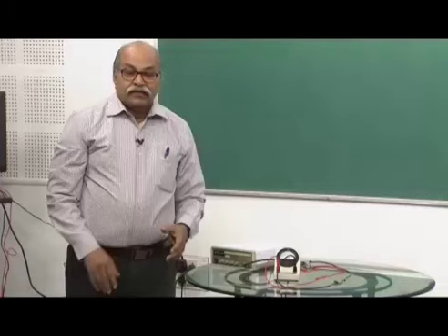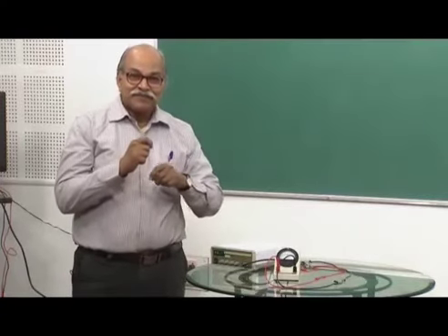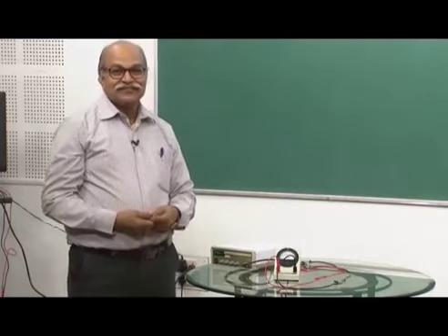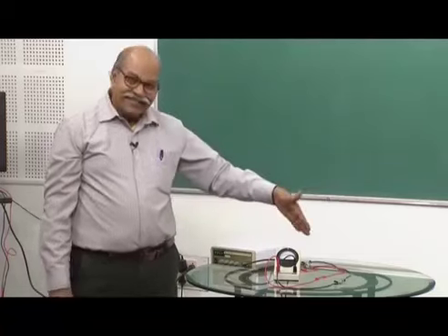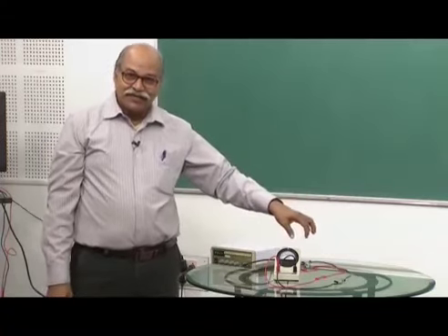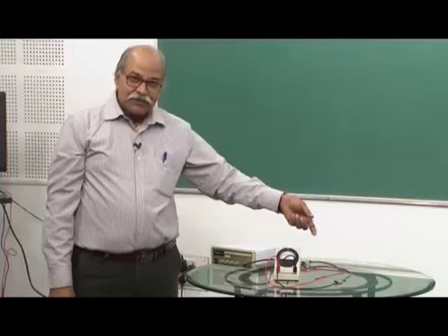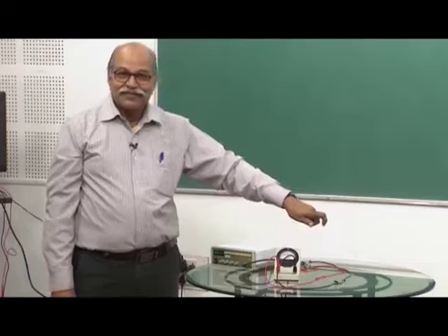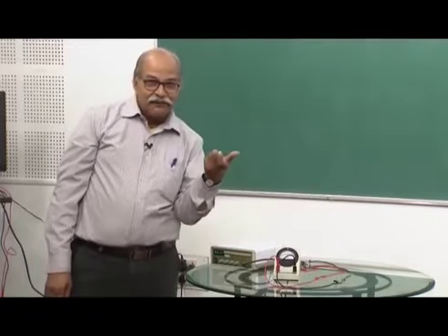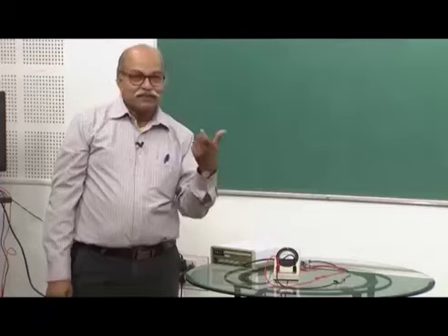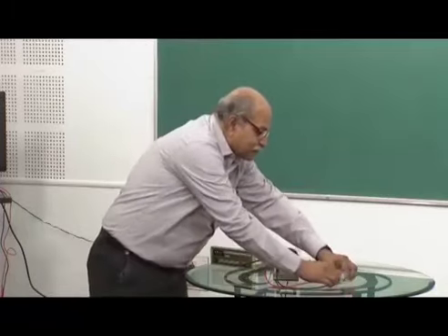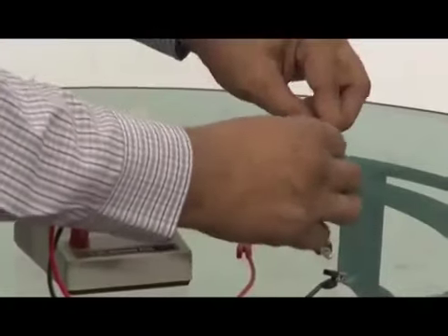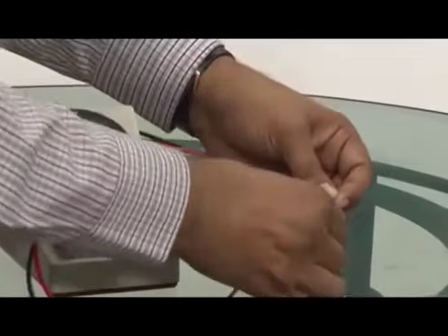Right. Now, let me reverse the polarity of the diode. What do you expect? Since this is AC, it will still work, but what was the positive cycle will become the negative cycle and vice versa for this diode. In the half cycle when it was forward biased, now it will be reverse biased. So, let me do that. I have opened this diode, inverted it and connected it again.